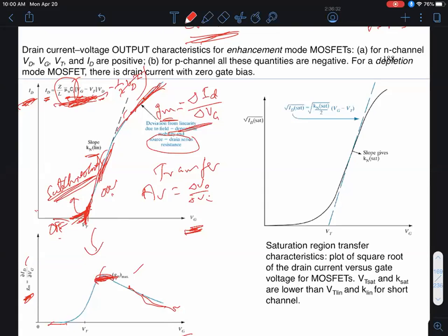Yeah, this is just a cartoon view. So you're saying that it should be kind of constant for a while and then go down. Yes. Generally, the region where it's constant slope is typically a small range of gate voltages. You get the maximum slope at the point of inflection of the curve. But there could be a certain region that's kind of flat here, right?